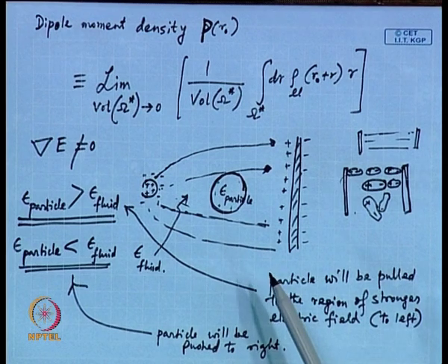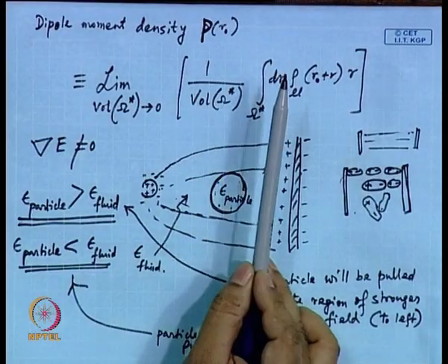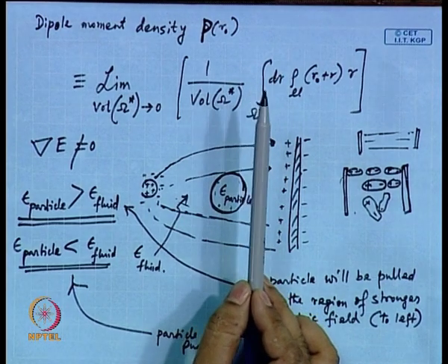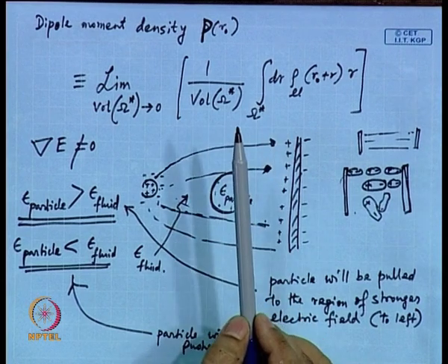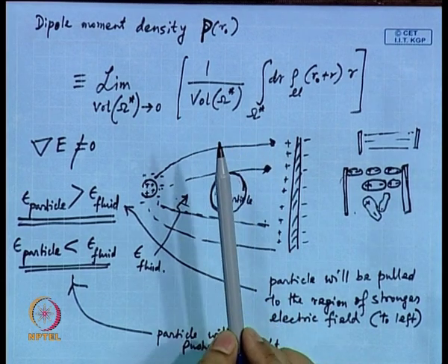So, near the wall the velocity would be 0 and away from the wall, near the central part of the channel, the velocity would be highest. So, the central part of the channel will come out first, and the layer that is next to the wall is taking the longest time, the most time, to reach the outlet.